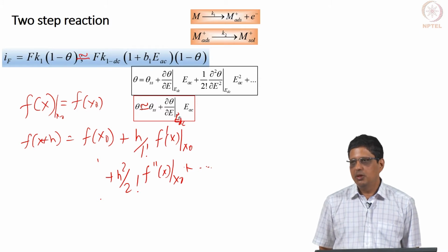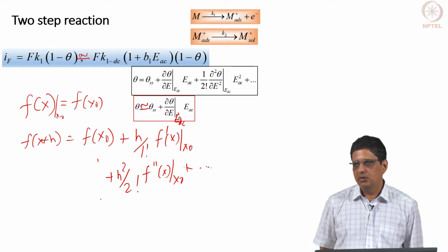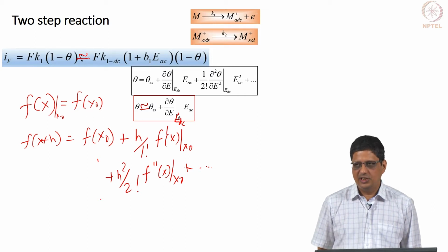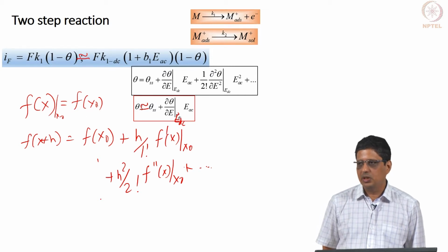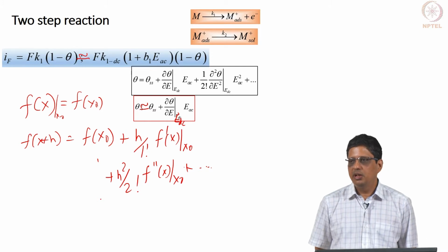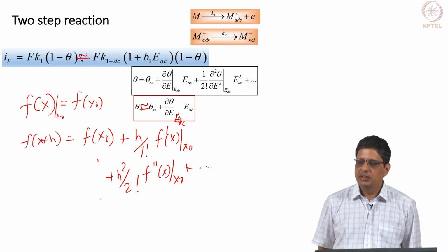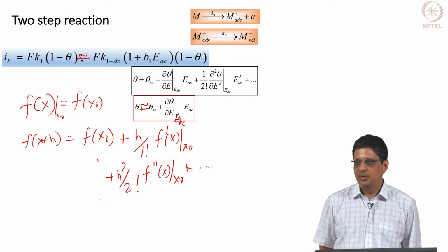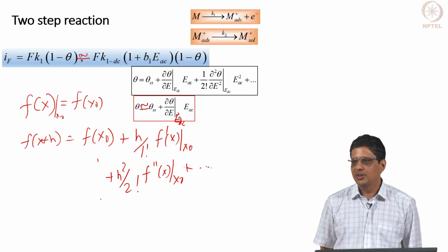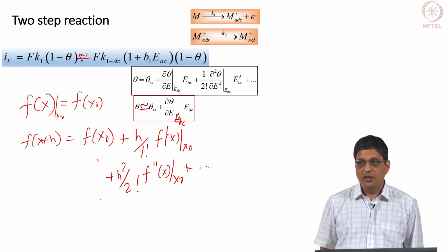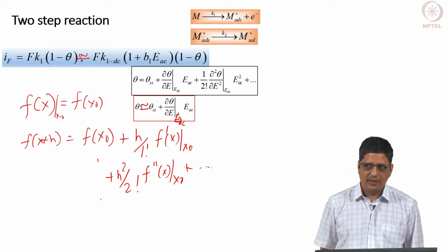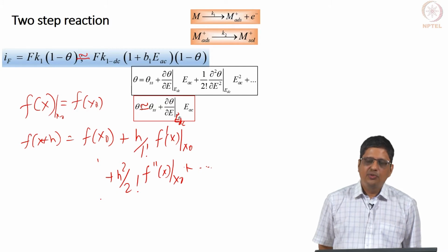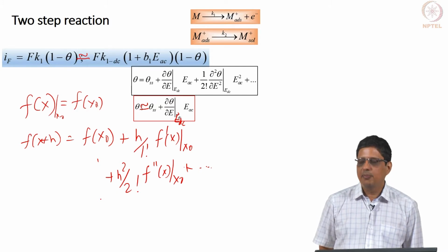5 millivolts, nobody will complain, but your noise level may go, noise level meaning the signal to noise ratio may not be good. Noise level is going to remain at whatever level it's in. 1 millivolt, everybody will be happy, but will people start doubting the authenticity of your data if it looks really good. So, the correct answer is it depends, but that probably is not going to make you happy. 5 millivolt to 20 millivolts you can probably manage. I do not know if it is going to be linear at 20 millivolt.